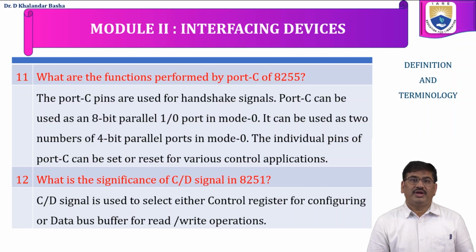The 8255 we can use in two modes of operation. One is BSR mode and the other is IO mode, where BSR mode stands for bit set or reset mode. So in 8255, by using BSR mode, we can set or reset the port pins of port C.